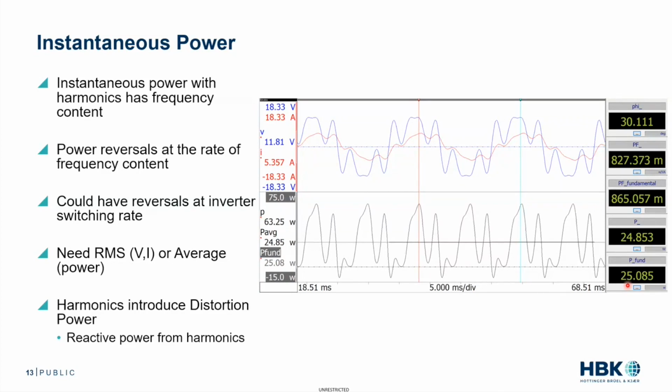So this is another circumstance where people will tell us, we get a different power value with your instrument versus somebody else's. Well, if you're filtering out the 5th harmonic in one instrument but not the other, you will see different power values. Even if it's just a little bit, there will be a difference, because which frequency band are you looking at?